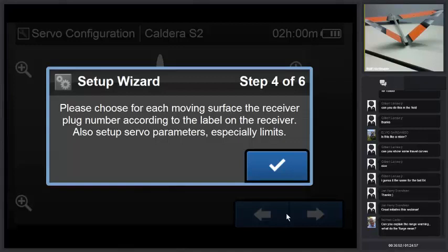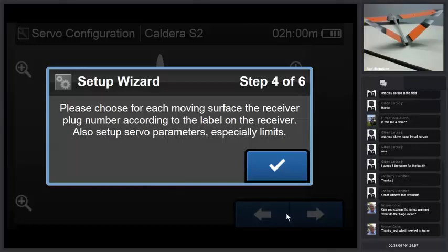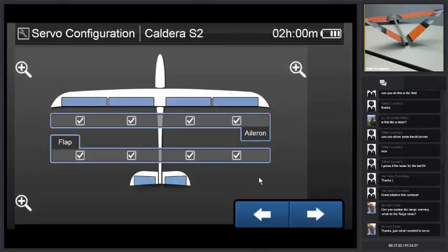What do you think is the minimum? The minimum to fly, I would say, is about 5. Okay. But when you're on 5, it's the absolute minimum. Yeah, but when you're on 5, it's like the antenna is broken or something else. So when you keep the 30%, it will be perfect. Yeah, and usually during flights, even with big models, it should never drop below 50%. But you also have the back channel, and the back channel is the default value of 1%? Yes, because it doesn't matter when the back channel drops, because this is just giving information from the plane. Okay.